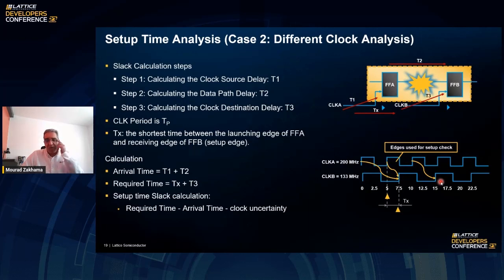So which one should we use? The STA tool will use the worst case scenario just to make sure that all these situations will work. And in this case, it's a 2.5 nanosecond timing constraint. And you may wonder, in the timing report, you may see that certain timing paths are constrained at 2.5 nanoseconds or 400 megahertz, but there is no clock that is running at that speed.